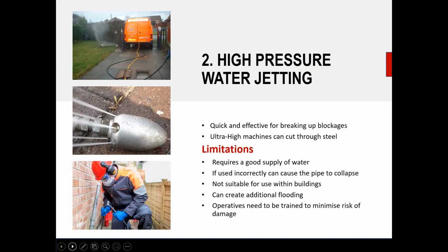With water jetting, you're actually adding water into the pipe. Therefore, if you've got an already flooded pipe, then you've got a risk of causing an environmental issue and subsequent flooding. The operatives need to have undertaken a registered training course, which is normally done through the Water Jetting Association, and it's a City and Guilds qualification or an NVQ.